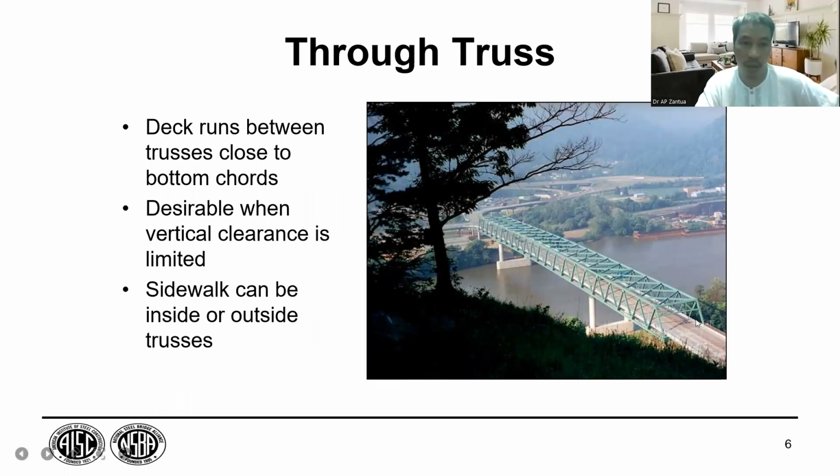The deck runs between trusses, close to the bottom chords. So in a true truss, the spacing between elements is wider compared to a deck truss. It is desirable when vertical clearance is limited. The sidewalk can be inside or outside the trusses. Just like in our own country, we have the Quiapo Bridge, which has a sidewalk outside the truss.